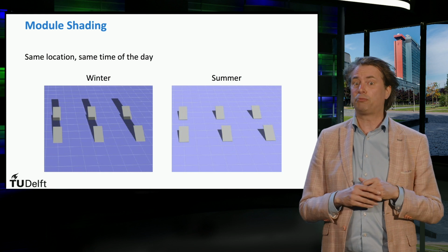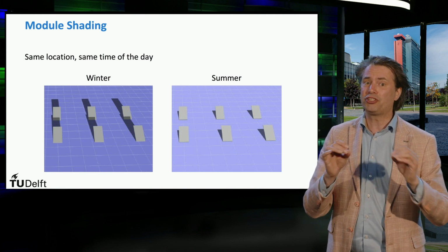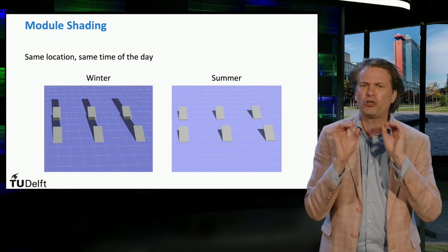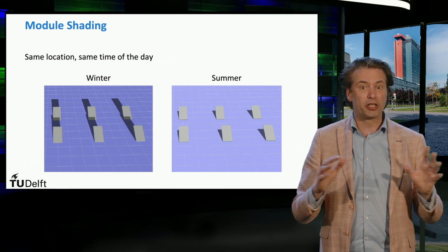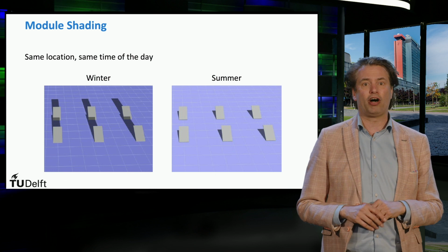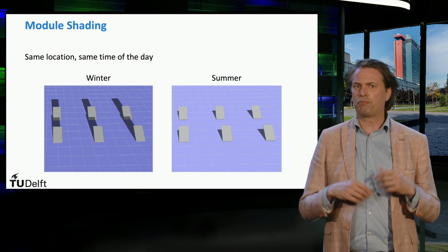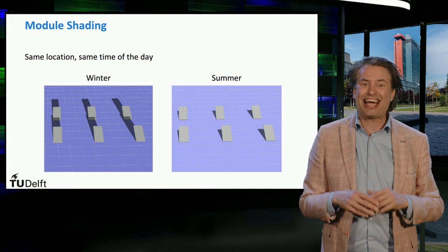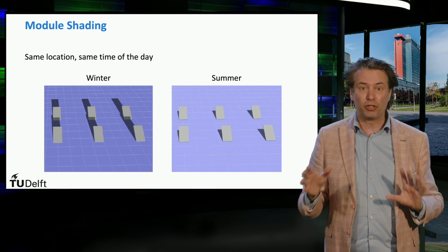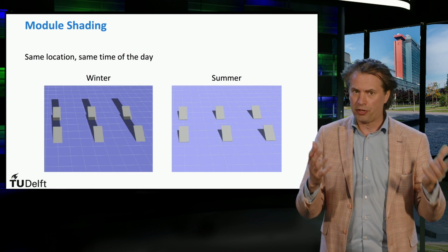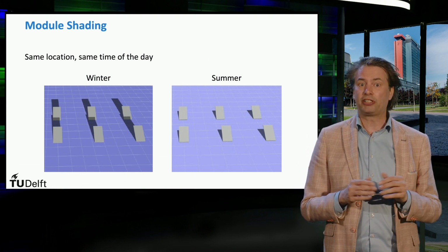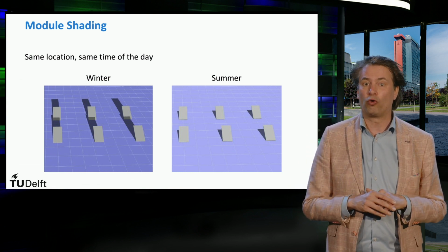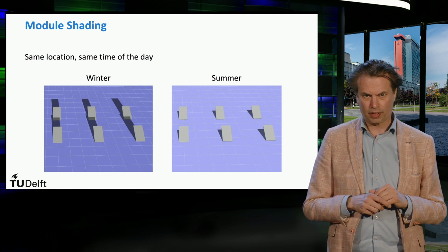This aspect has to be taken into account during the design of PV systems because it might happen that during winter rows get mutually shaded, lowering the yield of the system. Therefore, an optimization is needed to avoid accidental shading among the modules, which leads to an underperforming system, but also to avoid overcompensation, which increases the land or roof usage.